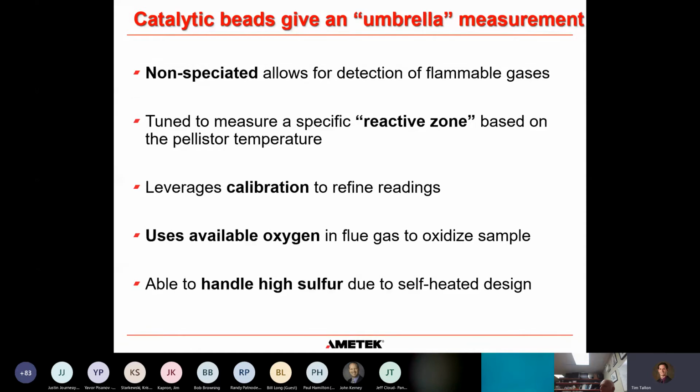And because of the pelistor nature, because of that resistor nature, the catalytic beads themselves are self-heated. So they're designed to handle high sulfur conditions because they're already self-heated. They're hot enough to handle any type of sulfur dew point, for example.